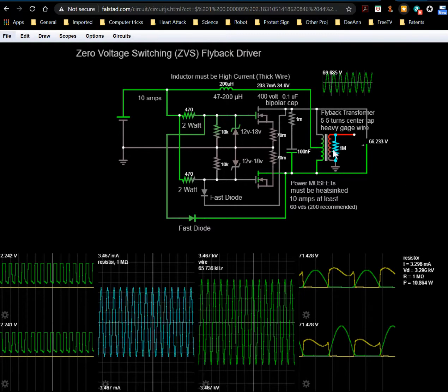But remember, you're dealing with a real-world circuit, so it won't be exact, because real-world inductors and capacitors have different resistances, and inductors, for example, have a little capacitance in them, and capacitors have a little inductance in them. So these aren't perfect, but it'll give you a good idea of what the value is, because it will have a resonant frequency, and that is true.